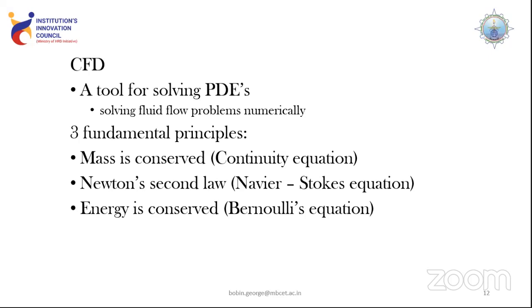For that, we have the fundamental definition of the continuity equation that we have studied starting from our 10th and 12th classes itself. Then you have Newton's second law. That introduces us to a basic equation in fluid dynamics, the Navier-Stokes equation. The Navier-Stokes equation says that momentum is conserved. That is the basic principle behind that. Newton's second law also states like that only. As I have stated in the slide regarding Newton's second law, you can't always have a general relationship. In that condition, we go for a partial differential equation, and such a partial differential equation is this Navier-Stokes equation.